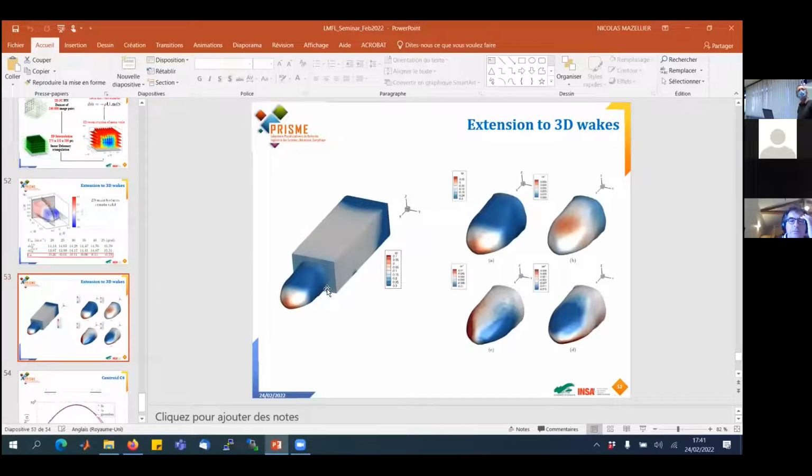Okay. You can see that the recirculation bubble doesn't cover the entire base, which is common on the Ahmed body. Okay, but is it okay? Your reasoning is okay, even if you don't capture the full back of the body. You think it's the drag because you speak of the CP on the reduced surface on the body. Yeah, here, if I remember, we've got something like 80% of the total surface. So it misses parts which are here, obviously, but at least the main scenario remains valid.